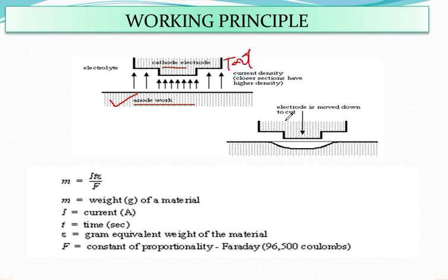This is your tool, and you can see there is a current density, and I have already told that current density has a relation inversely proportional to the gap. If the gap is more, the current density will be less. If the gap is less, your current density will be more. So you have to remember this particular relation.